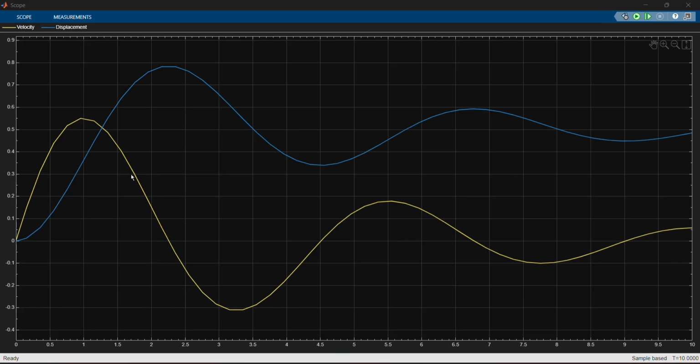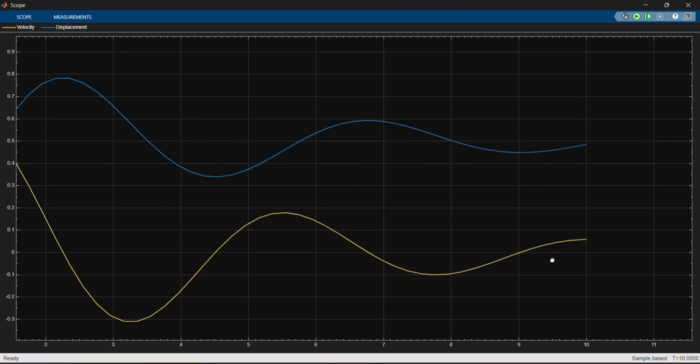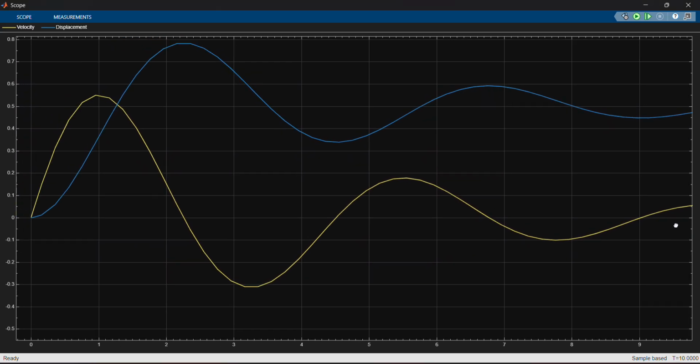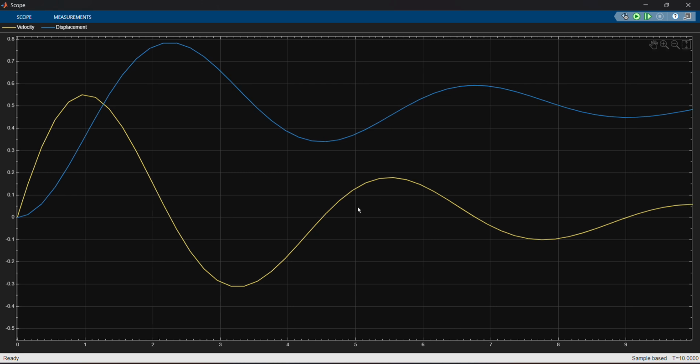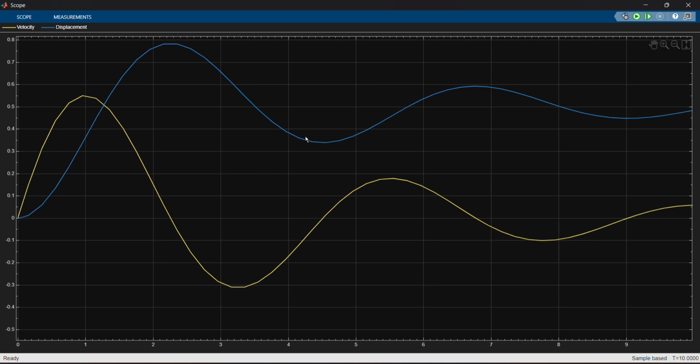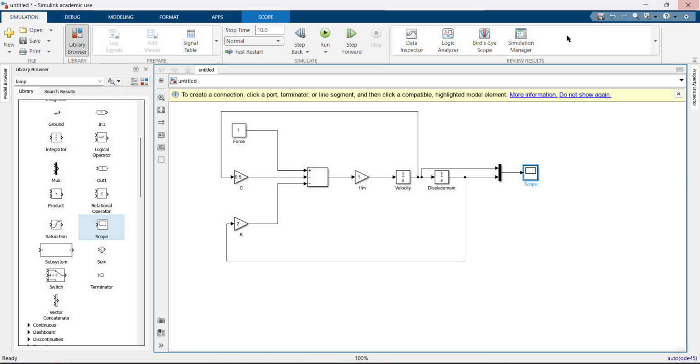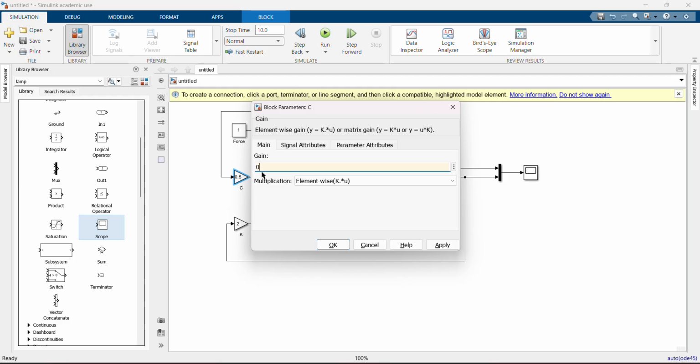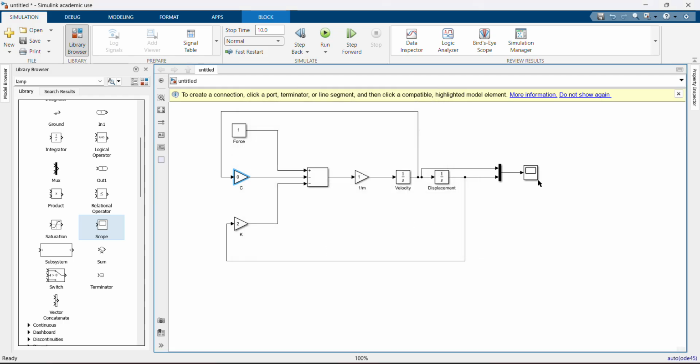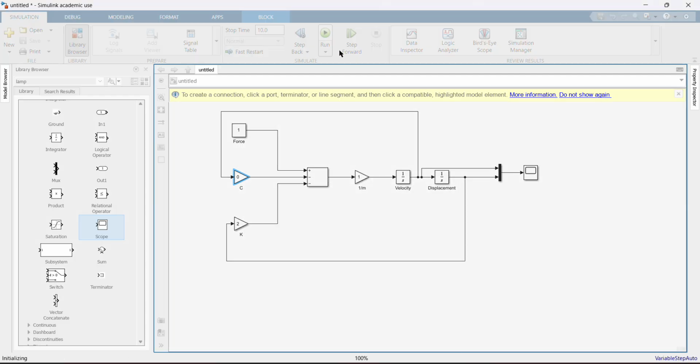I'm clicking on the block and now you can see it starts as a uniform wave, and it is still a wave at the second interval, but only after that it becomes a flat line. So now this is a generally damped one. The previous one is an overdamped oscillation. So now finally let's give an underdamped oscillation to this. I'm going to give the value of c as 0 and I'm going to run the simulation.